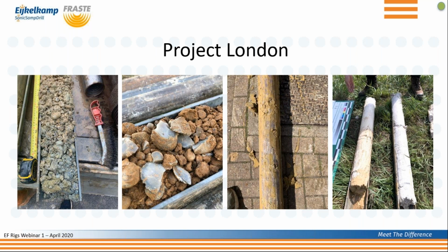Okay. Do you think also the dual wall core barrel helps quite a lot with that in the very difficult to drill materials? The dual wall core barrel, yeah, it's an amazing bit. It's what you use in the tougher ground conditions. Okay. For the audience, the dual wall core barrel allows you to use a bit of water or air while taking a sample, but the air outlet is arranged so that it doesn't flush away or contaminate the sample, but it still allows drilling really hard material.